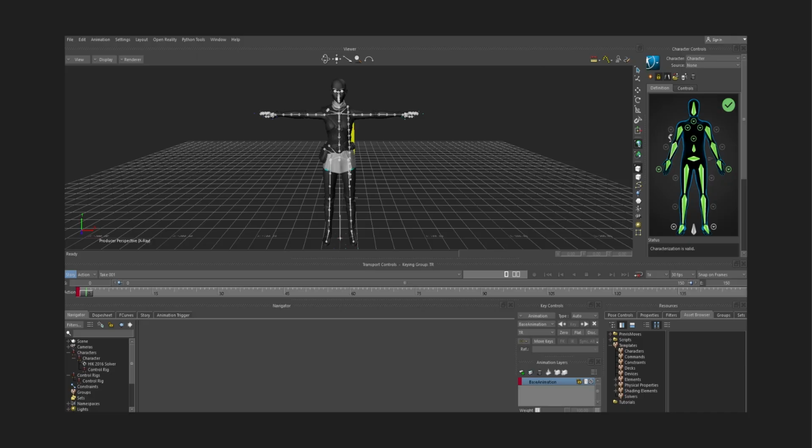During motion capture week, I was assigned the task of characterizing Echo, and this is important as I'd be able to retarget our motion capture data onto Echo's rig. Using MotionBuilder was an advantage as well, as I'd be able to map Echo's rig using the HumanIK template that comes with MotionBuilder.